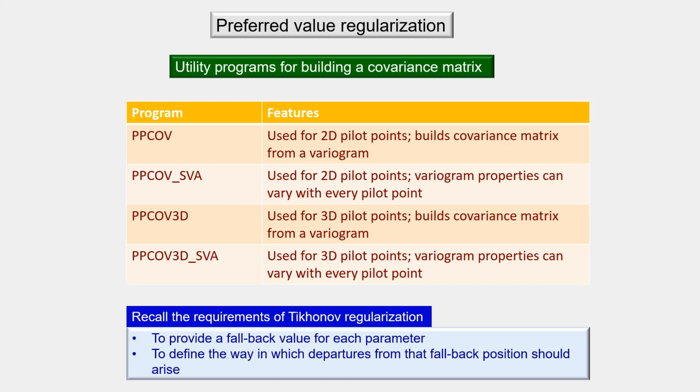This is where we have information. We're putting pilot points in areas where there's high information density in anticipation of the fact that heterogeneity will arise on that scale. Further out in the model domain, where there are no boreholes, where there is no information, pilot points are placed more sparsely. We don't expect to see heterogeneity arise on a small scale in those parts of the model domain.